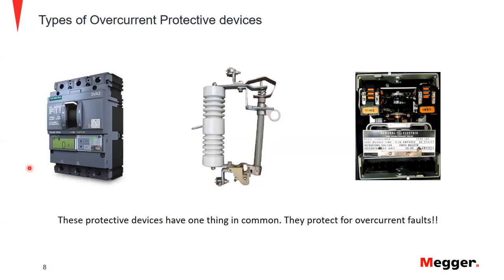It uses a fusible link, and the fuse senses the fault condition, and the internal fuse link will melt, opening the loaded circuit. The link will also be blown clear of the insulator housing, and if you've ever tried to put a fuse back into service while the fault is still there, it is a very loud blast, and you definitely have to protect yourself.